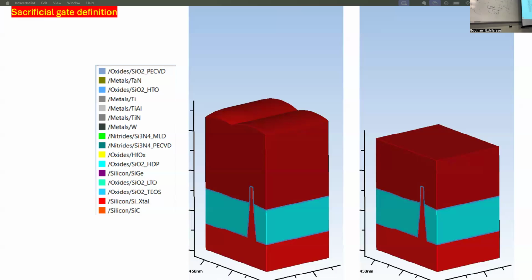So before that, you have another alignment, right? You have the metal, right? No, this is also self-aligned. Yeah. You will deposit metal everywhere. When you define your first gate, this polysilicon gate, yes, there's a litho step. But to do replacement metal, there's no litho step, because the replacement metal is just going where the polysilicon was originally defined, right? Yeah, I'll talk about that.